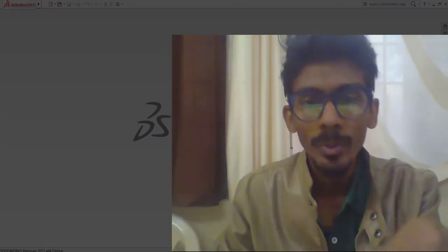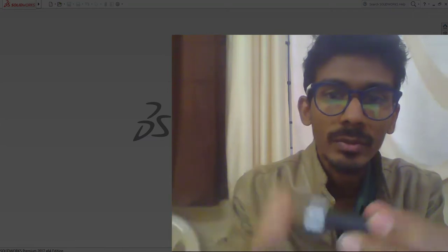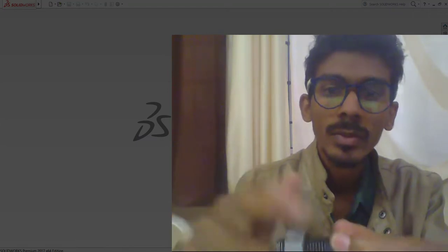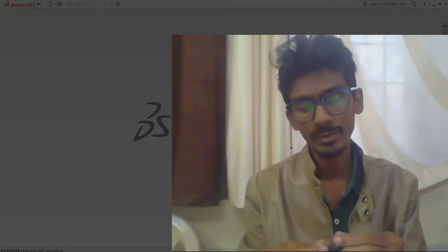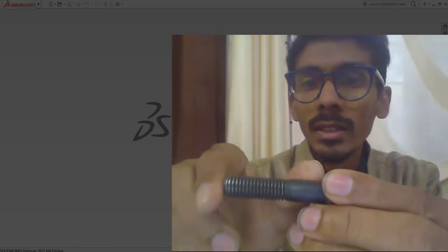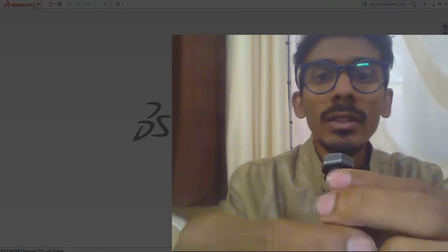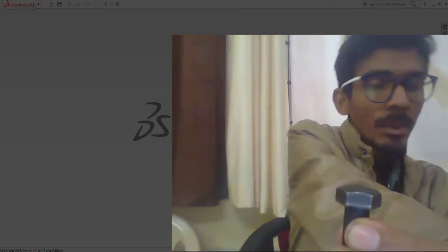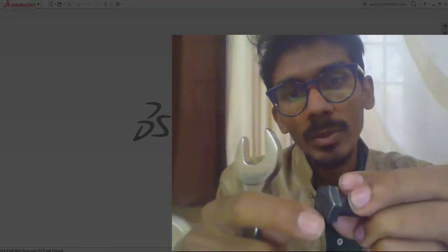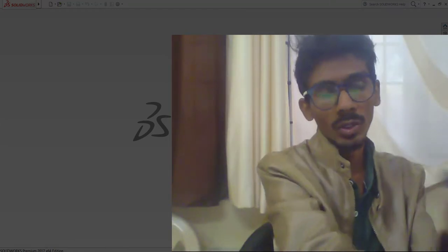In this video we are going to make this bolt and nut with this cool animation. For this video I have taken a 10 mm bolt, and this 10 mm bolt has a length of around 50 mm, 36 mm thread length, and this bolt requires a 17 mm spanner, because this hexagonal shape has 17 mm diameter. So let's try to make this bolt in SOLIDWORKS.